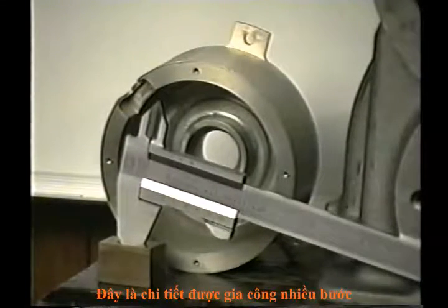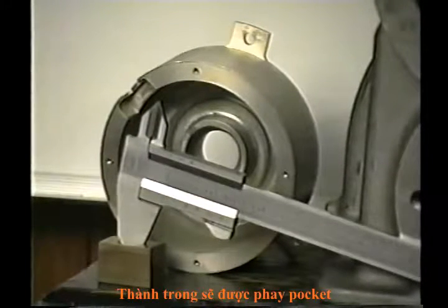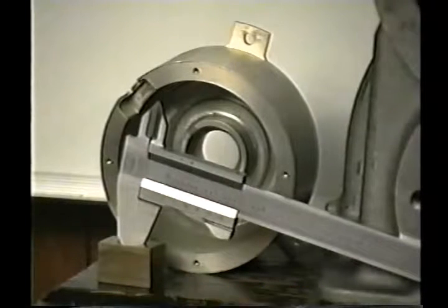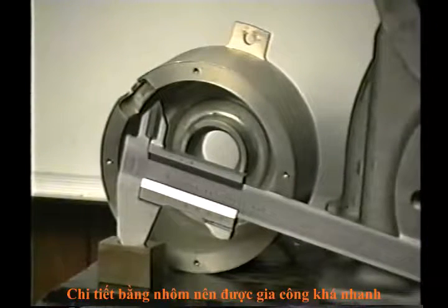This part has a variety of operations. There was a turning operation to begin with, but all of the inside is actually contour milled out. It was not bored out. And there's a little recess. There are a number of holes. There are 1, 2, 3 to 4 tapped holes. It's an aluminum part, so it could be run quite fast.